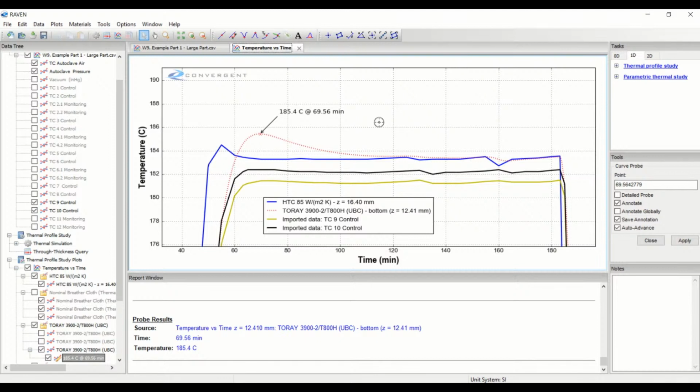And so very likely there is some heat transfer occurring out the edge of the part, and that's why we see no exotherm essentially within these parts: there is actually some heat transfer conducting away from these thermocouples out the edge. So if you wanted to capture this quite well, you would want to potentially move to a 2D or 3D COMPRO simulation, which would be able to capture those edge effects.